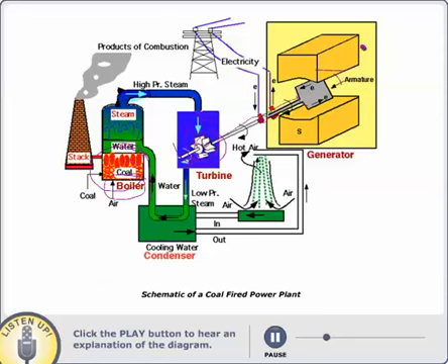This generator is nothing but a magnetic field. In other words, that magnetic field is created by these poles, north and south, and these yellow ones are basically the magnets. And in between these two poles, this electrical conductor, a copper wire, which is turned many rounds around the armature, turns. The two ends of this wire are hooked up to a load or to a transmission line. So when this conductor is turned in a magnetic field, you get the electricity.